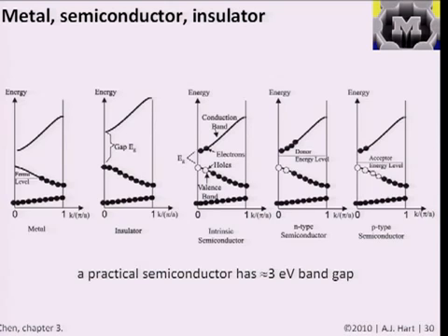And the really nice thing about semiconductors, and why they're so useful in a lot of applications, is that you can move around this highest energy level by something called doping. You start with a lattice of, say, silicon, and then you inject into it some atoms of another material that has extra electrons or a shortage of electrons. They call them N-type and P-type materials, and they'll shoot in, say, phosphorus or arsenic or boron atoms.